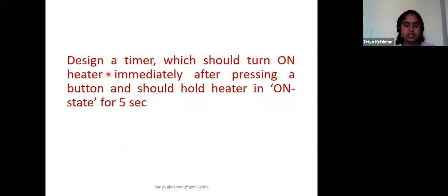One more. Design a timer which should turn on a heater immediately after pressing a button and should hold the heater in on state for 5 seconds. Once I switch on, the heater should go to on and it should stay in on state for 5 seconds. Yes, it's correct. It is the monostable multivibrator. So hope you all understood the session. Any queries, please post to us.